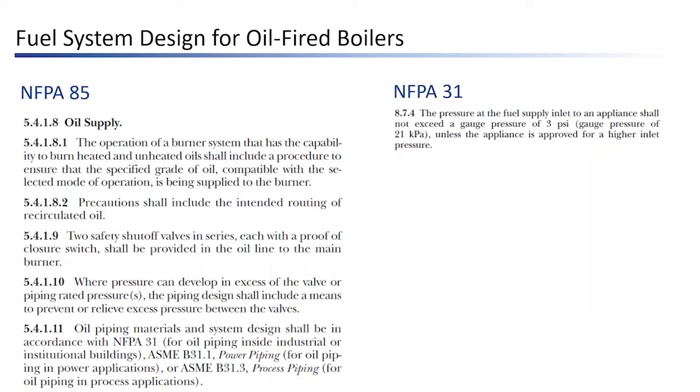And I put in the appropriate similar paragraphs from NFPA 85 that makes no regard to a specific pressure. It just says that the piping that you use and the valves shall be rated for the pressure intended.